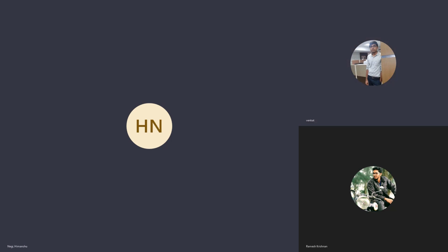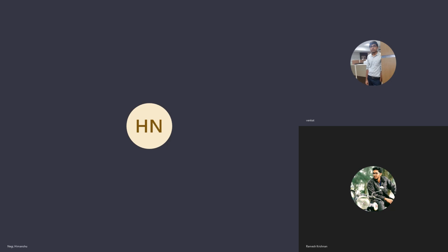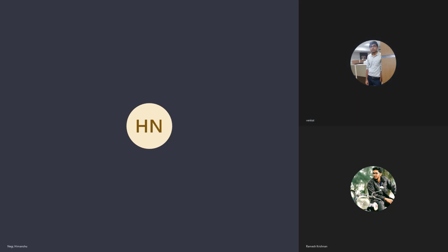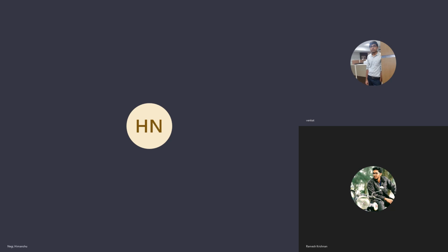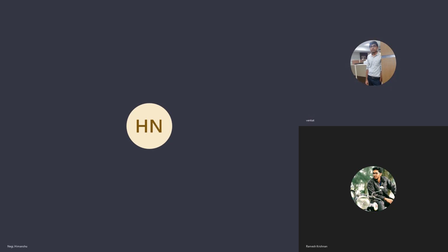You are saying that when the cable and the transmission line are both connected through a mutual earth mat, then such incidents will not happen. Am I correct? It will still happen, but I think the problem will be less. The damage will be lesser on this part compared to just arresting them like that, right?